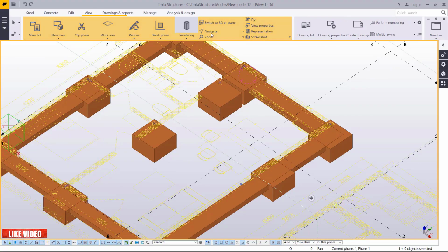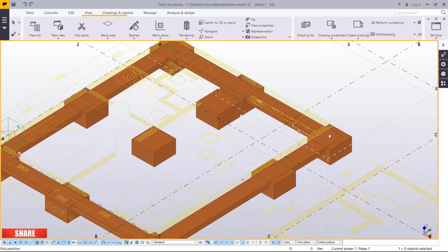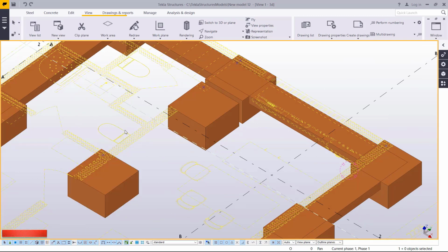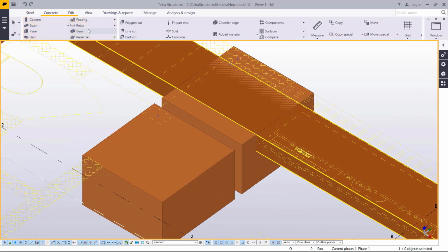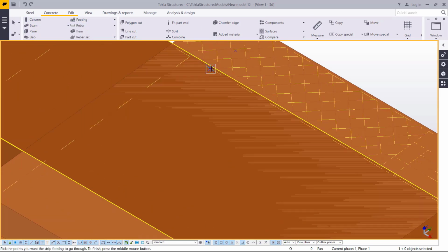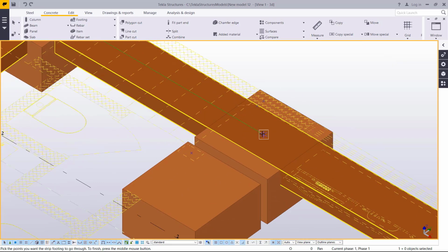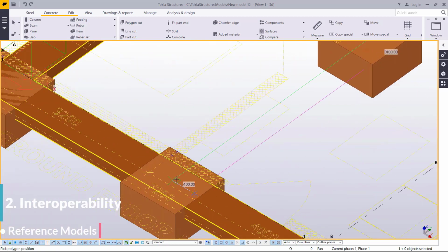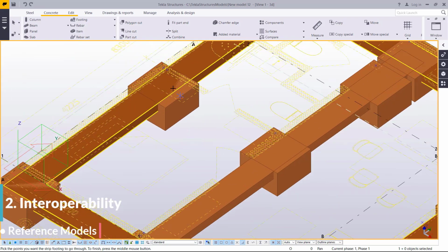And if you come to view here, you'll come and check that. So we're moving step by step. So I'm going to add another strip all the way from that spot to this far end. So with the help of these points, we'll be able to create that. I'll come to footing and pick on strip footing and locate that on that position. Make sure you snap on the accurate point. So that should be accurate, and we'll move all the way to this location, and press your middle button on the mouse, and you've created your strip footing.